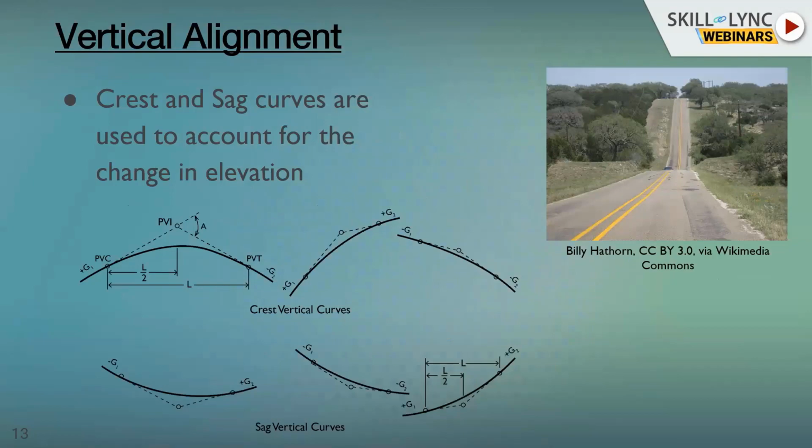Although this process seems very easy, there will be a lot of constraints. As a highway engineer, you have to take considerations from the drainage team and from the structures team. They will give the bridge elevations, and you have to match that. Drainage people will say the drainage profile should be this much below the ground, and we have to match that. So all these issues are to be addressed while making a design.